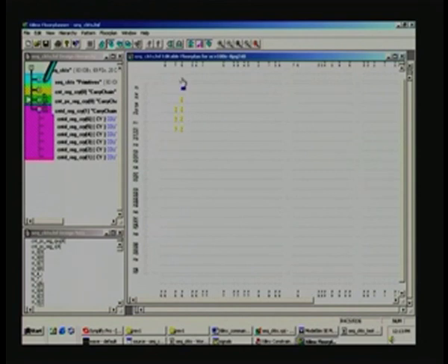And another advantage is, as I mentioned earlier, there are two teams working on hardware as well as software. One team will be freezing on the hardware design right at the inception, along with your Verilog coding in parallel and concurrently. That would be possible in this FPGA platform, because you can always come to the fag end of this, where we are now, and change all the pins to suit their hardware engineers' design. To suit those particular pin assignments, you can redo this pin constraints, you can change it.